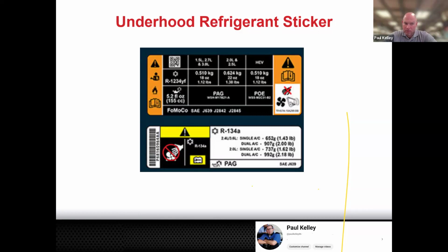Well, the main thing that comes to mind for me is the compressor has parts. There are different types of compressors, but if it's an axial piston type, there are actual pistons going back and forth. How well do you think that's going to work with no oil, right? You're probably going to end up seizing that compressor, blowing it up.